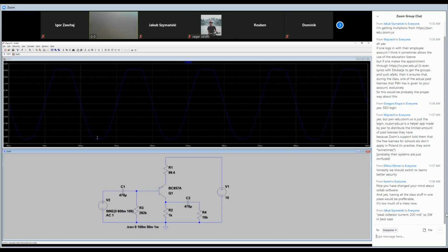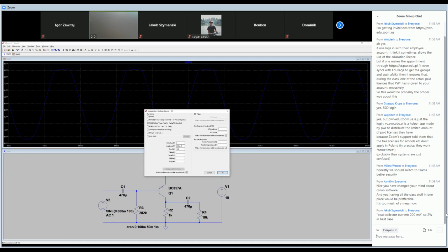Why? In the one case, we are going to the limiting of the VCC. In the other case, we are going to the saturation of the transistor. So as you see, we can put here so huge the input signal, due to the amplification of the current, and as the consequence the voltages on the output, and completely turn off or completely turn on the transistor, saturation of the transistor.